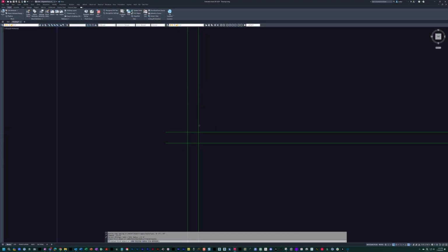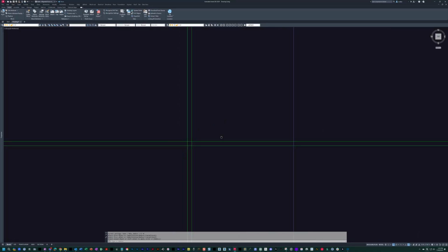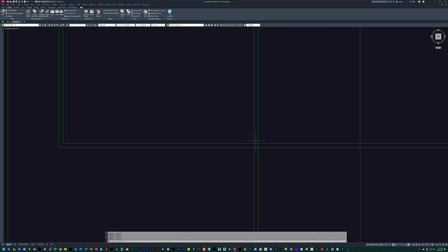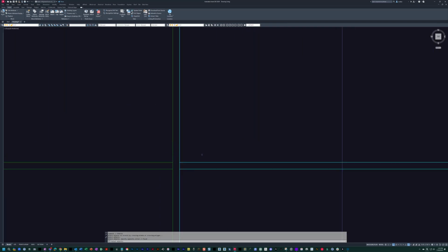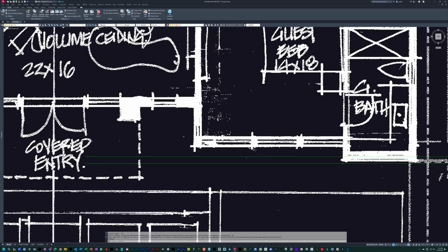All right, so I'm going to offset this 8 inches, and if I turn my background image off, I can fillet these, and this is just going to be the beginning of my corner. I'm just going to trim it right here because really I'm going to need these walls over here. So then we'll fillet this and fillet this. Turn our background back on.